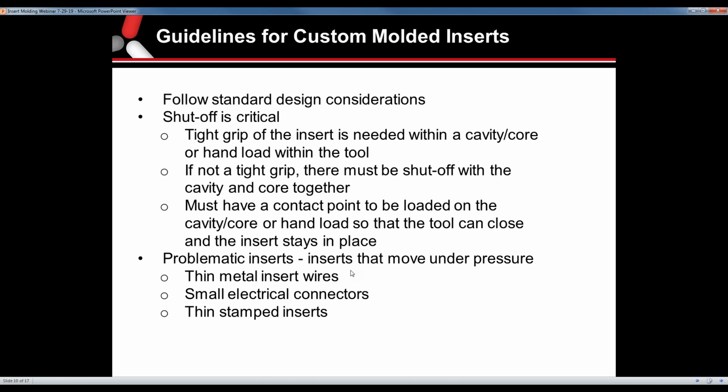Again, the tolerance, sometimes, as John used the term, float. We tend to make our locator pins for those inserts to the high side of the tolerance. And we do segregate parts at the press that are too loose and avoid using those. But the tolerance of the inserts itself sometimes can cause you some issues that will take a couple of adjustments to make sure they're nice and tight.